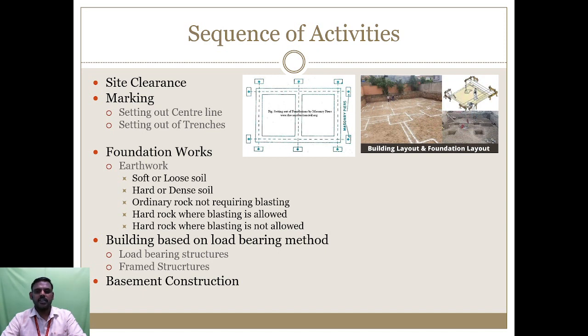Okay, in the initial stage we are giving a marking with white powder. Based on the white powder marking, we have to construct pillars, brick pillars, masonry pillars. On the top of the pillar, we have to mark the location of the center point, so that it will help us maintain a proper alignment of the building foundations.